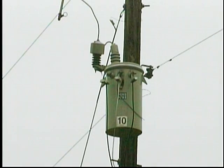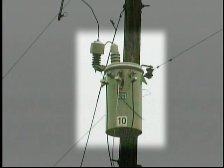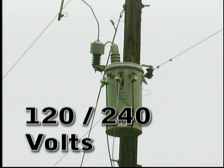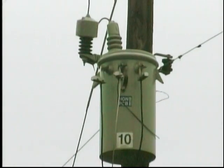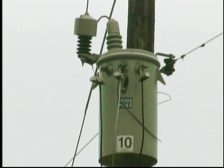Now, let's take a look at some examples of single-phase transformers that are commonly found on distribution systems. This is a single-phase, single-bushing transformer. It provides single-phase voltage, typically rated at 120/240 volts, to a secondary load. On a single-bushing transformer, the primary bushing is generally mounted on the top of the transformer housing.